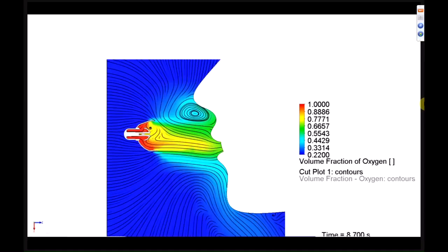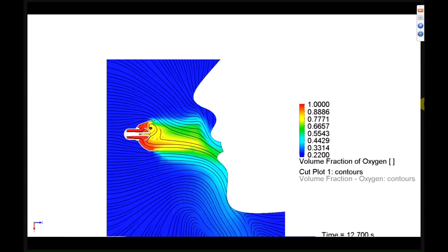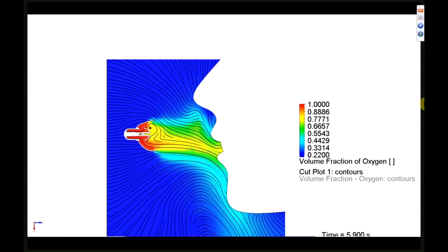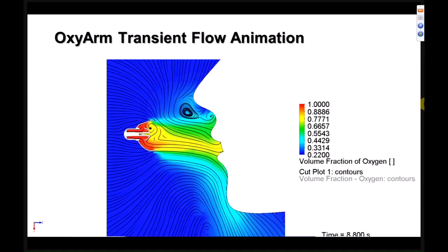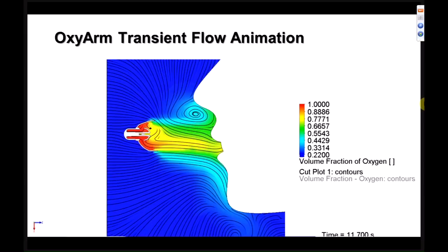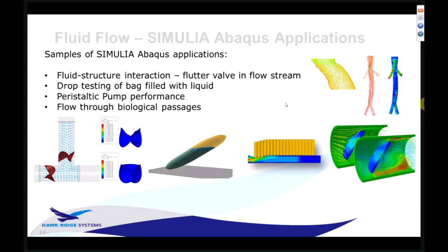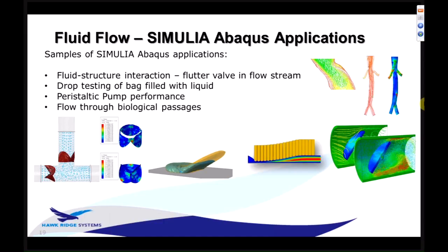So there are a couple of limitations to SOLIDWORKS Flow Simulation. One, we cannot analyze moving geometry or deforming geometry at the same time as we analyze the flow situation. We're also unable to represent free surfaces of fluid. So for those next step analysis conditions that do exceed what's possible in SOLIDWORKS Flow Simulation, again, we look at SIMULIA Abaqus.